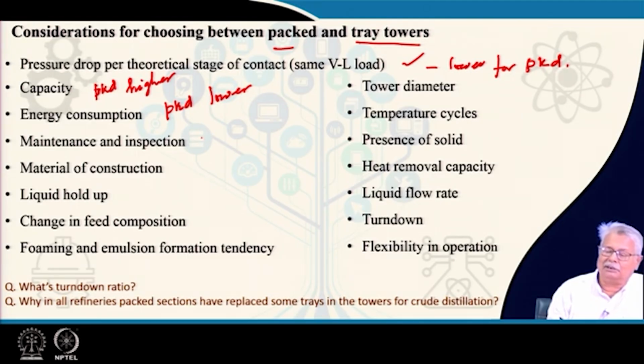So, they are required to be periodically repaired, inspected and maintained certainly. In the same way, a pressure surge in case of packed tower will normally disrupt the packing, and once disrupted, it has to be repacked, at least the top part of it. So, I will not basically decide between the packed and the tray tower, and I will say they are more or less equivalent.